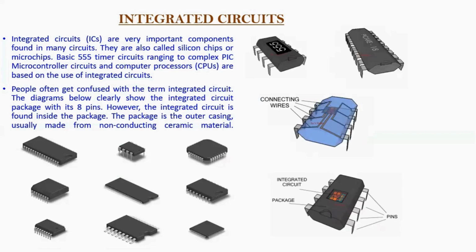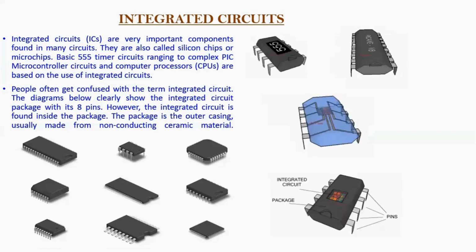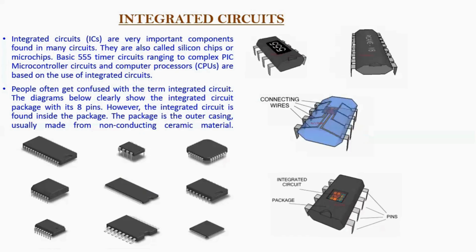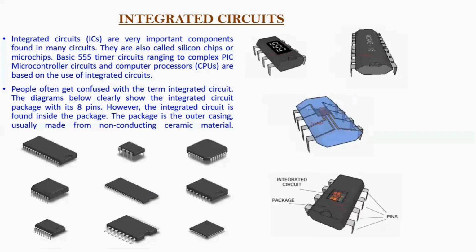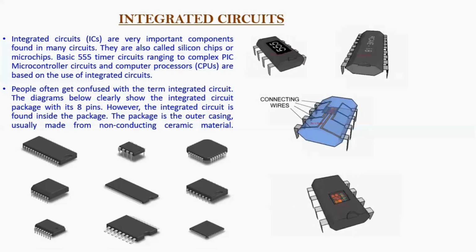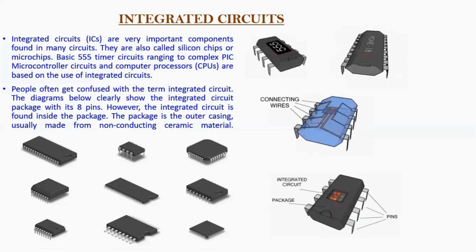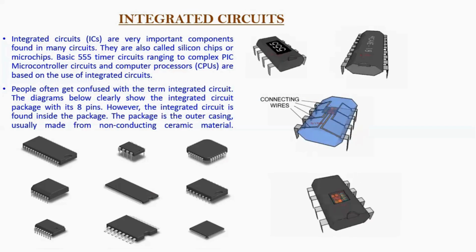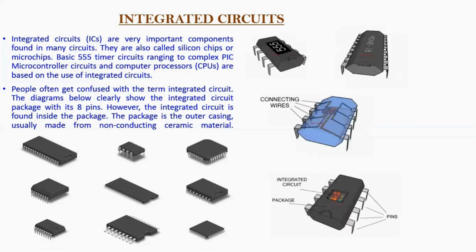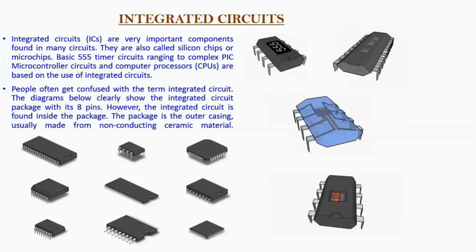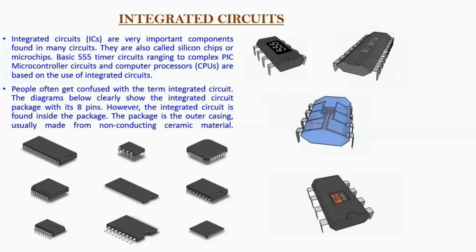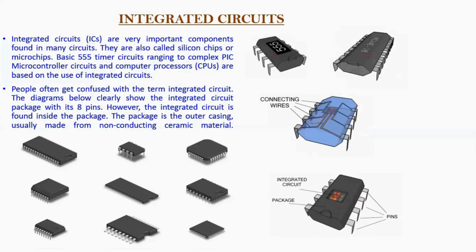Okay, right. It can start from 3 pins, that means the number of pins can start from 3 and go up to many pins. If it is a microcontroller, somewhere you will find pins of 200, 250, or more than that also. So different packages of ICs are available. You can see 3-pin ICs are mainly not transistors, but what is called a regulator IC, or linear power regulator IC. Microcontrollers and memory ICs all come under digital ICs. We'll study about that. So this is about an IC.